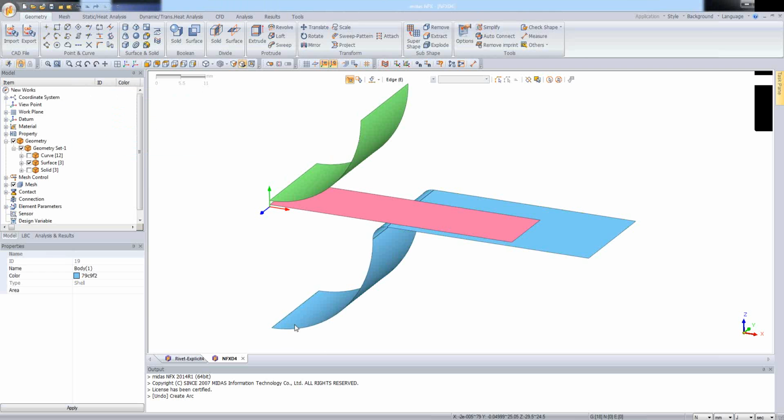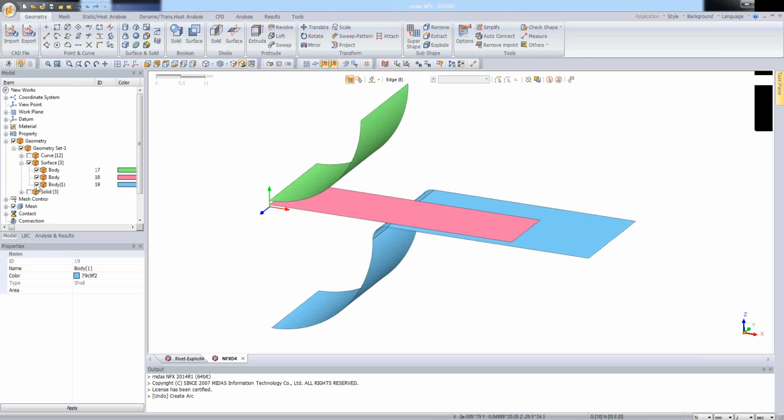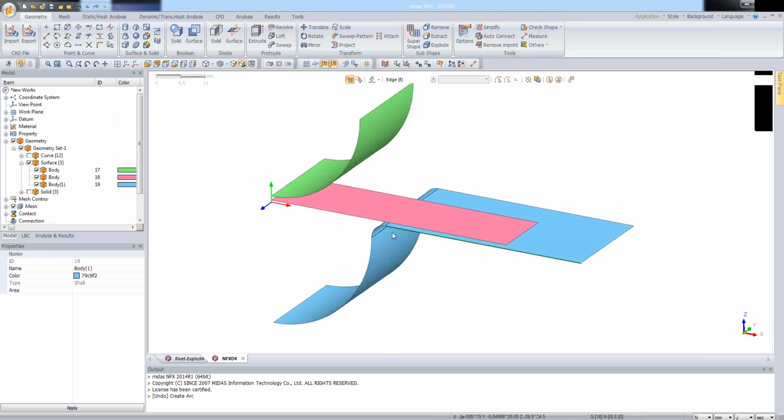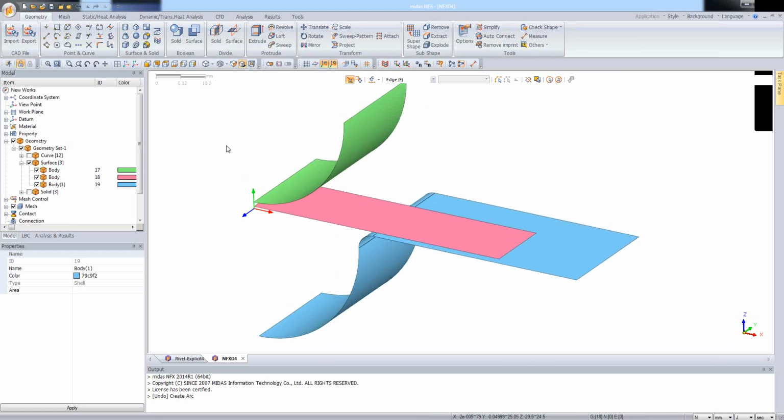And let's click on OK. So now we have 3 surface bodies. And there is one thing left related to the geometry. I will break the edge for the sheet metal because this will be necessary for the mesh seeding. So I'm using this command, break curve,